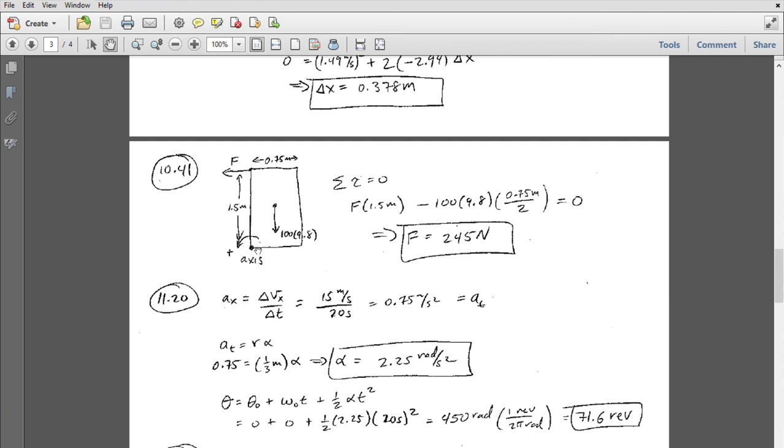We could imagine there being a little foot pad here at the bottom front of the refrigerator, and one at the back too. Normally there are forces being applied from both of them, but at the point where it just starts tipping, the force on the little foot at the back of the refrigerator goes to zero. Just at the point where it's going to zero, it's still in equilibrium.